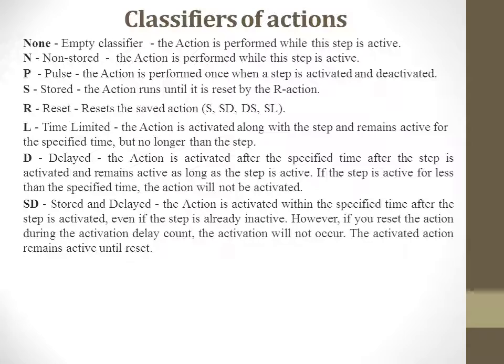SD, stored and delayed: the action is activated within the specified time after the step is activated, even if the step is already inactive. However, if you reset the action during the activation delay count, the activation won't occur. The activated action remains active until reset.